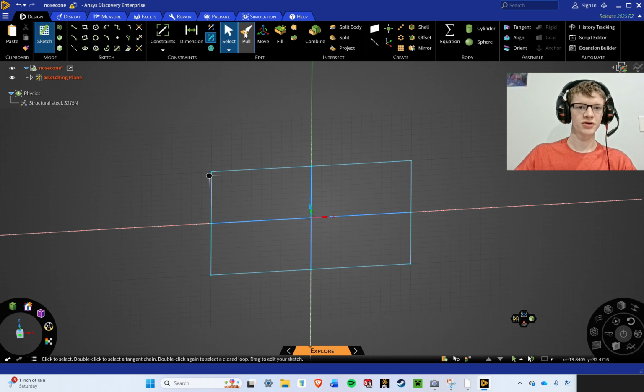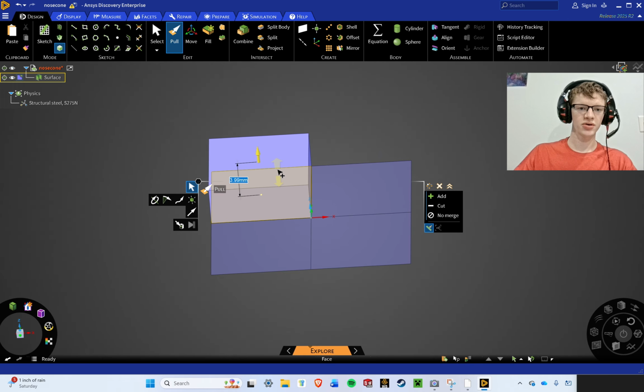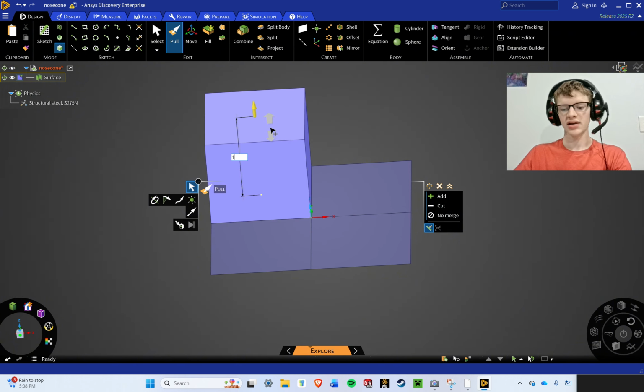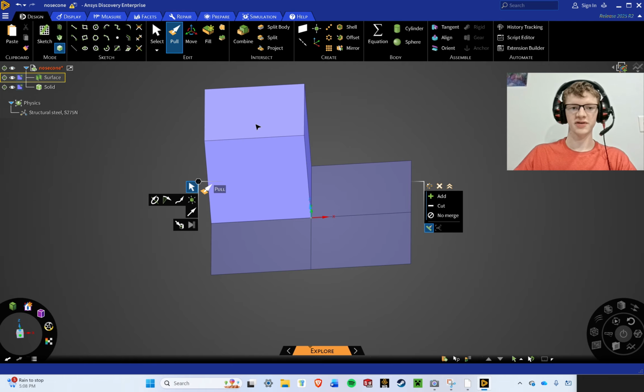We're going to move from sketch to pull, and that is going to let us take these 2D shapes and then pull them up. Now, if you pull this, you can see it's got a dialog box where we can edit the text. So with your mouse still on the left mouse button, type 10 in and press enter. And now if your finger's still on the left mouse button, it's not going to do anything. You can take that finger off.